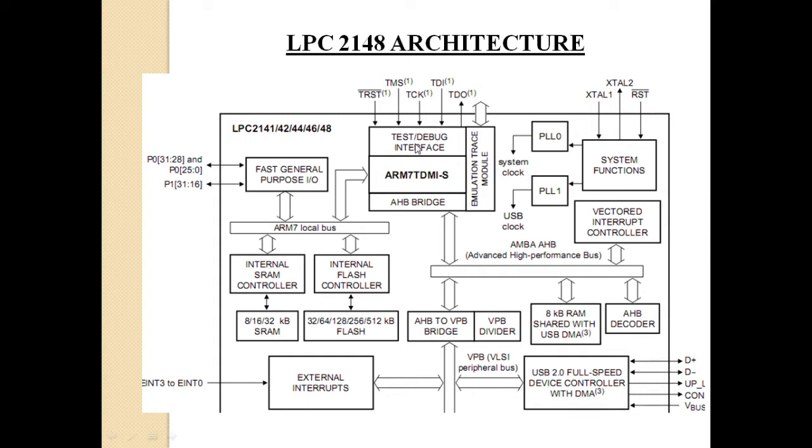We have seen that it has on-chip debugging support. That means using the debugging interface, you can connect it to debugging hardware directly, with no need of any other intermediate device. So this is your actual ARM processor, the ARM7TDMI-S. This block is your ARM processor, and the other things are the peripherals. So how will you connect your ARM processor with the other peripherals such as timer, ADC, etc.? By using something known as a bus.